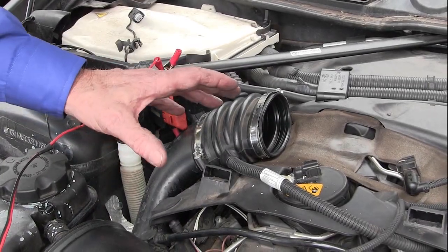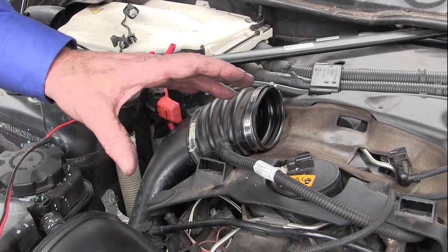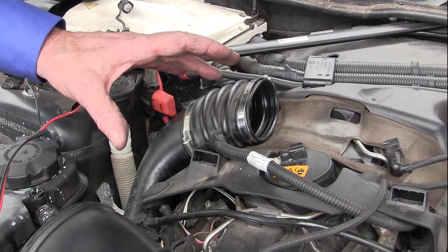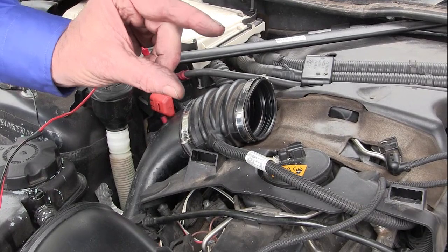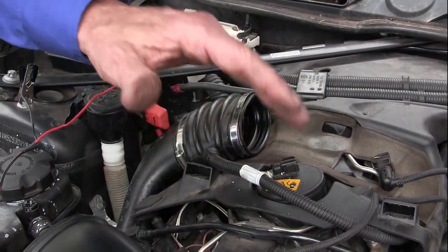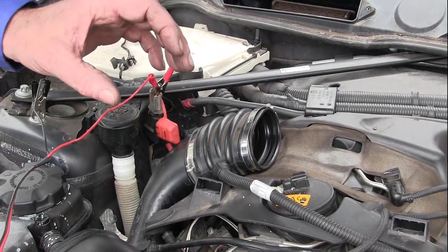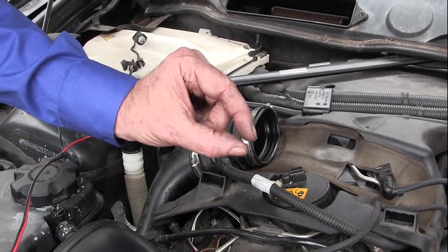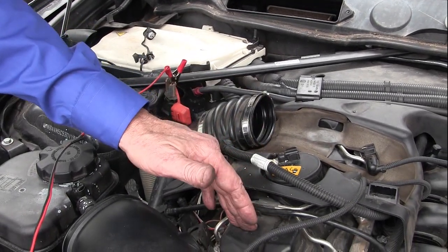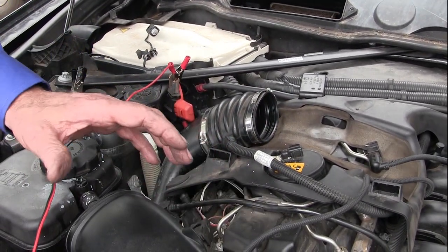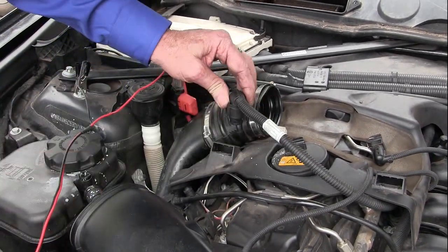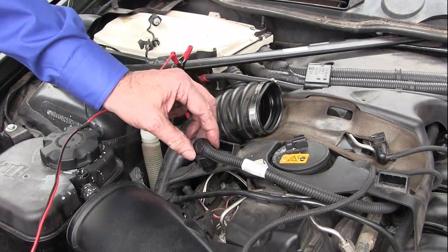On this BMW N55, this incorporates a Valvetronic system. A Valvetronic system is where the engine is throttled by the valve opening and not the throttle opening. So the throttle valve is open all the way up, and the valve opening is maintained very slight, and as I want more, I get more valve opening due to a rocker assembly. We don't want that when we're cleaning, so on this system, we're going to pull the Valvetronic off of the system.